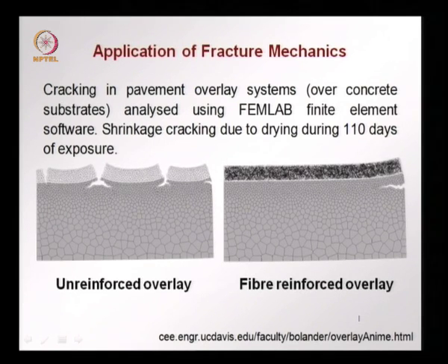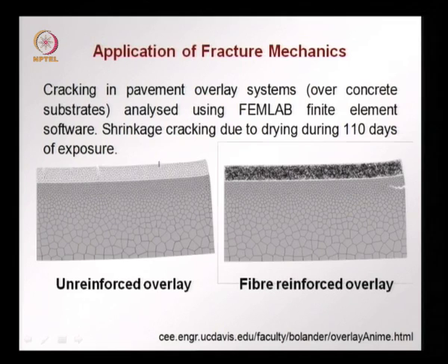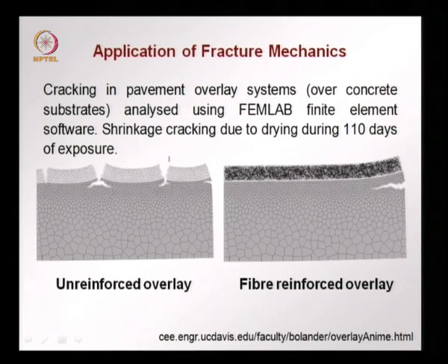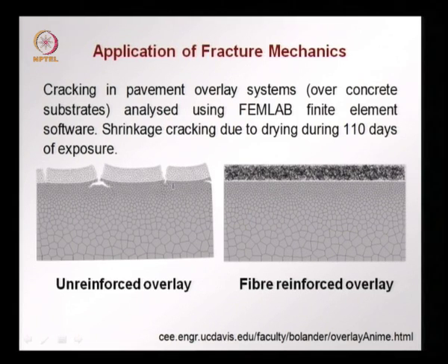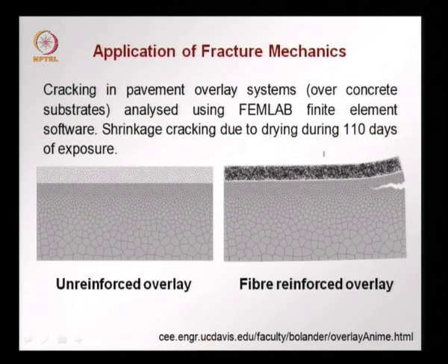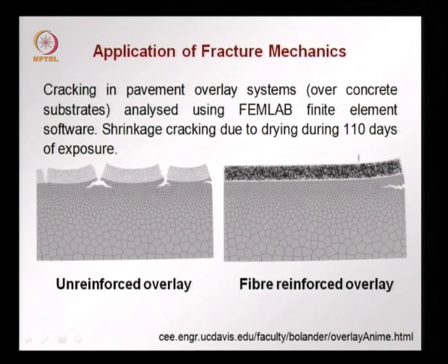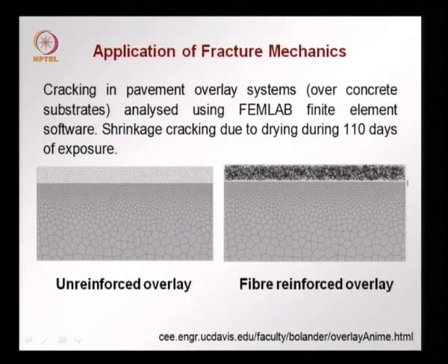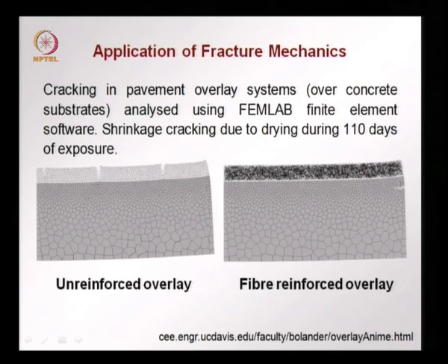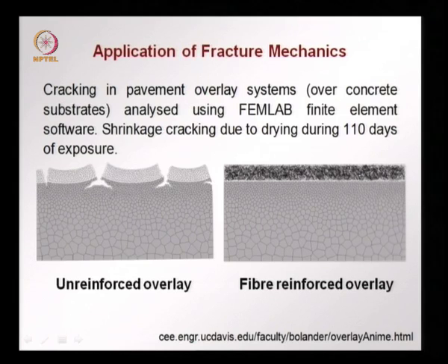You see on the left that the shrinkage causes stresses in the overlay which cannot be resisted by the plain concrete. The fracture toughness is not that high, so we have a crack through the overlay at several places. In fiber reinforced concrete now, the fibers cause toughening, there is a higher fracture toughness of the overlay. So even though there is shrinkage, the overlay does not crack, but the deformation causes a delamination running through the subbase instead of creating cracks in the concrete.